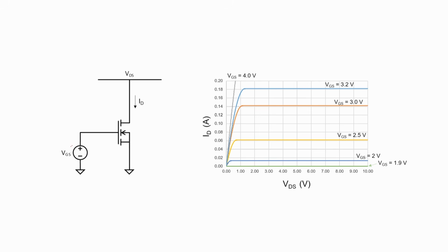As long as you keep the voltage here on the gate maintained at 2.5 volts, then you can expect a relatively constant drain current regardless of the drain voltage that you apply to that transistor. That means that the MOSFET functions in this region almost like a perfect current source. Over here at the left side, though, we see that the curve kind of bends down. Therefore, we can almost identify two distinct regions of operation when it comes to these curves.